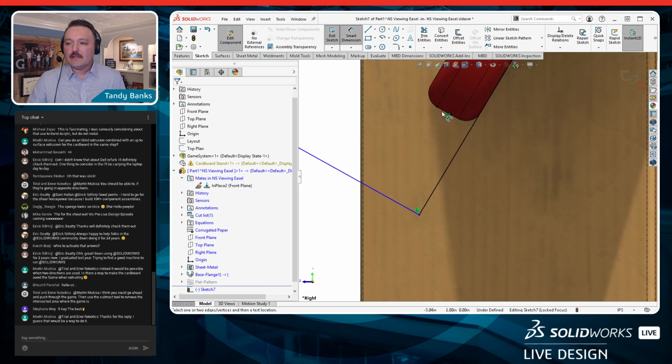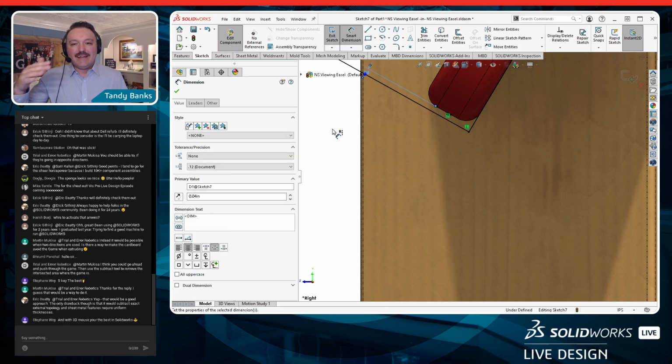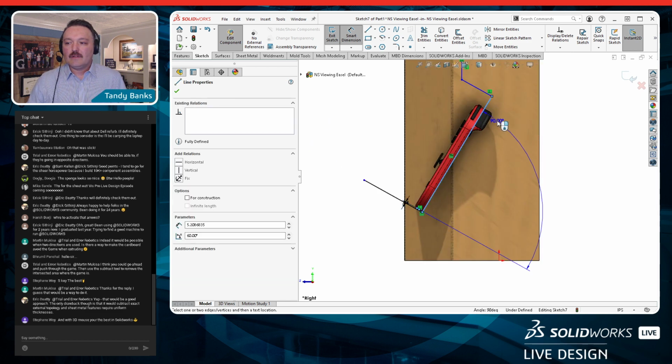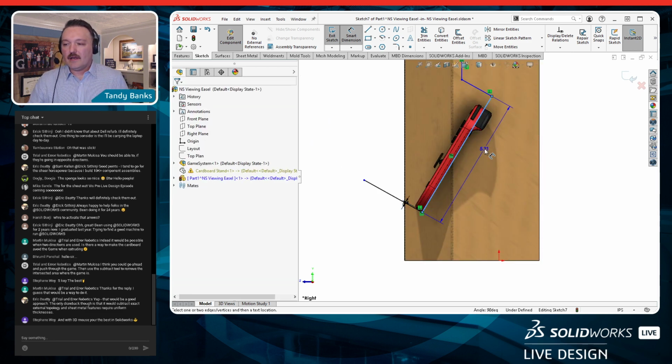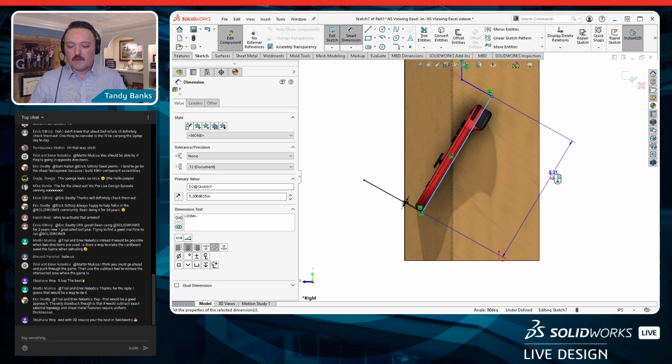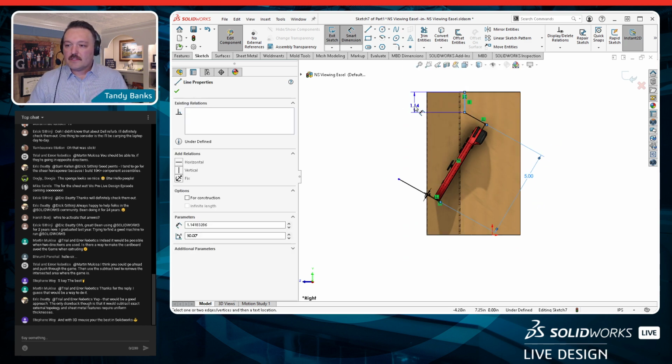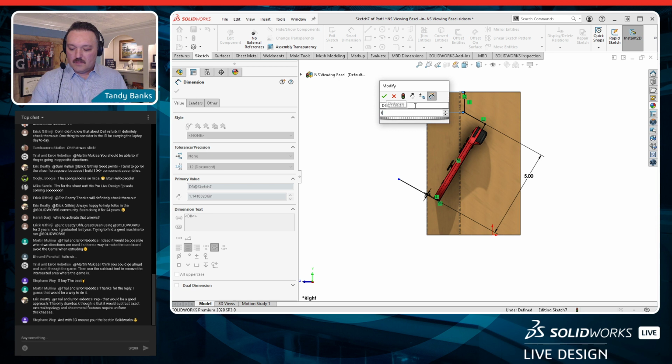My design intent here is that I want the bottom of this box, that cut, to be about 40 thousandths off the bottom. And then I'm going to want, again, measurements here. I want roughly 5 inches. And if you guys know or don't know, as you move our Smart Dimension tool, it's going to try to do vertical offset, horizontal offset, depending on where we move our mouse cursor. But if you right click, it'll lock that orientation, and that way we can come over. I'll specify that to be 5 inches, and then we're going to catch this front. I'll give it 1.5 inches.